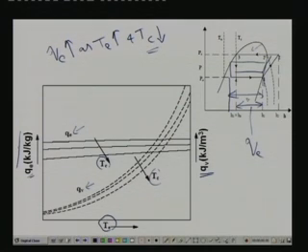And you can also see the effect of these temperatures on volumic refrigeration effect. How did we define volumic refrigeration effect? If you remember, QV is defined as H1 minus H4 divided by the specific volume of the refrigerant vapor at the inlet to the compressor. That means the specific volume at this particular point. Now you can see that for a given condensing temperature, as you increase evaporator temperature, the volumic refrigeration effect increases very rapidly. You can see that by this dashed line. Why does it increase rapidly?